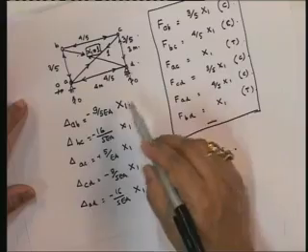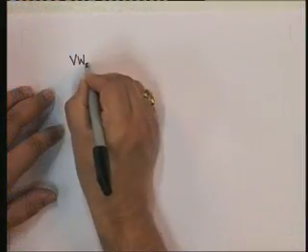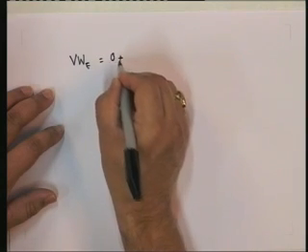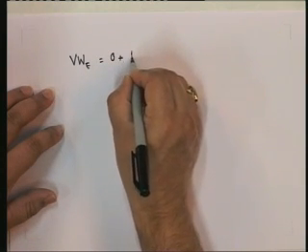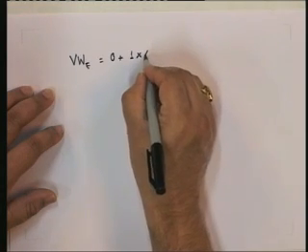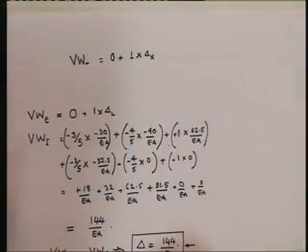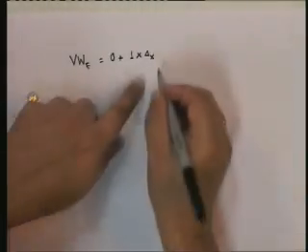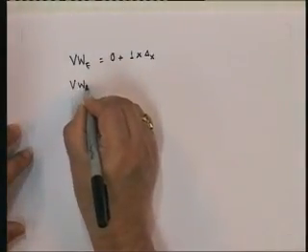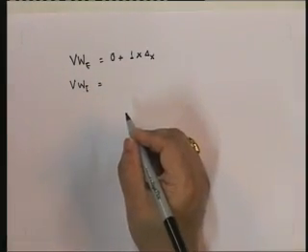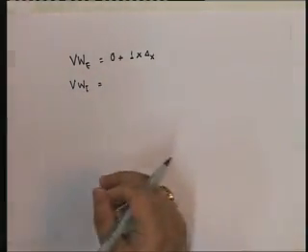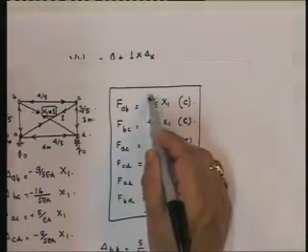Now to find out, again using the same virtual work principle, the displacement: the displacement is equal to external virtual work, all outside excepting for this is going to be equal to 1 into delta due to x. See, this original one is delta due to the load. So this is delta due to load. This is delta due to x. The internal virtual work is going to be equal to, if you look at this, the displacement multiplied by this.